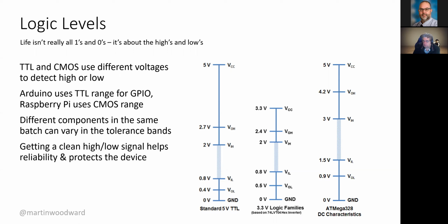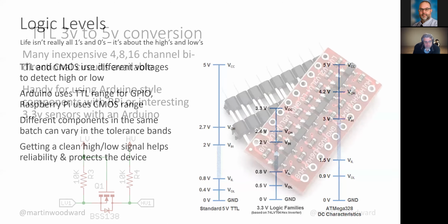So really the last problem to solve was that all the buttons worked off 3 volts, but controlling the NeoPixels, for example, doesn't. It works off 5 volt logic, not 3 volt logic. So we needed to somehow convert, because even though the Raspberry Pi is powered by 5 volts, it actually uses a logic level of 3 volts on its logic line. So we needed to somehow convert those, and that was pretty straightforward.